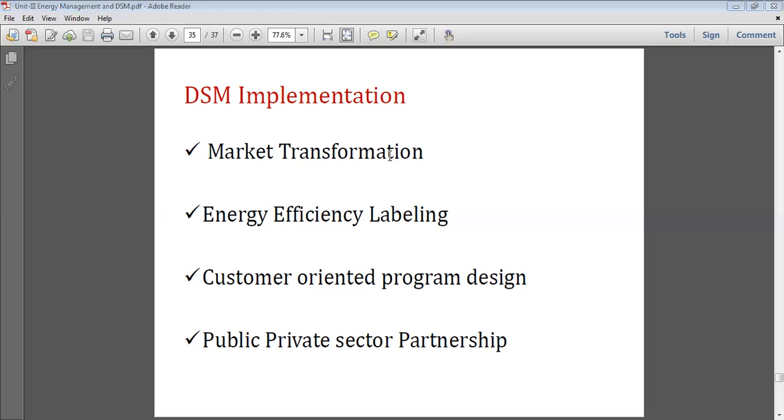Whereas an energy efficient tube lamp is available. It is rated with 5-star and 3-star ratings. In the market, the name is True Light. Okay, and if you just see the wrapper, you find that the consumption is 36 watt, whereas the lumen output is around 2400 lumens. So it is found that the consumption is the same, whereas the lumen output has increased. So it is the star rating. It is the difference between a non-labeled lamp and a labeled lamp.